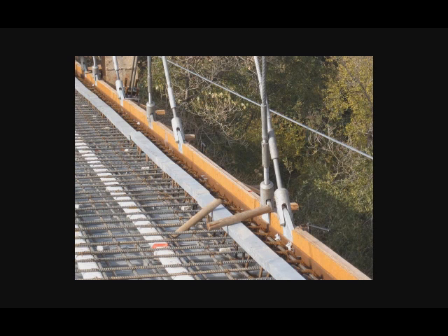So that is one approach where we have the stringers and the deck separate for the tie girder. The other extreme is shown here. This is the Happy Hollow Bridge. If you remember, that's the pedestrian bridge in San Jose, California. And what you see here is at the right edge where the cables are attached, there's formwork, the wooden thing, this is formwork for the deck. But then you can see just the top of the tie girder. This is a small bridge, so the tie girder is a lot smaller than what we've just seen for Blennerhassett Island. It's just a WT section. So that's one line of defense for our tie force.